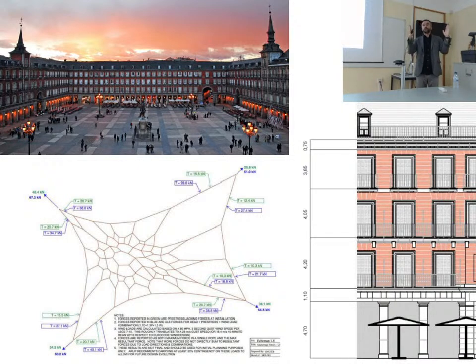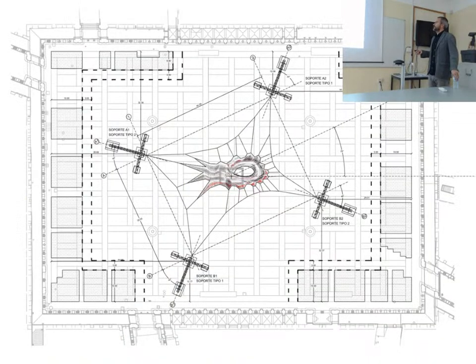To avoid this effect, we have to have big dead loads. But those big dead loads we have to take into consideration, because we have a floor, so they could not be too big. We needed big areas to try to match the actual design load of the floor. These are the values of the reactions. We have something like 6 tons of reaction. It's quite high. And this is the position we chose for placing the piece.